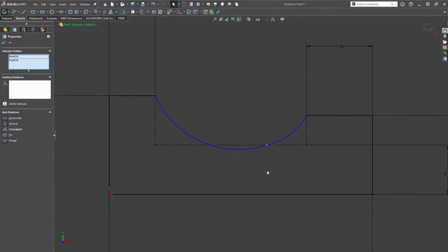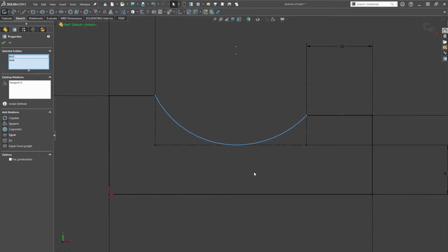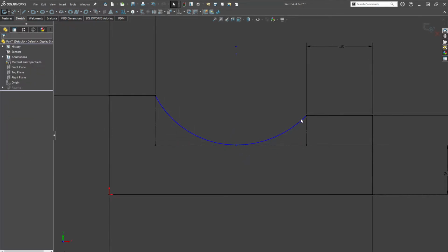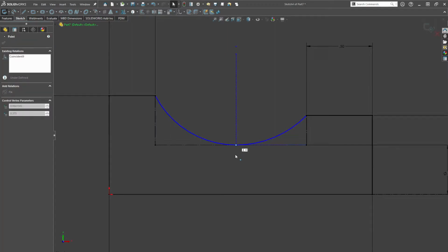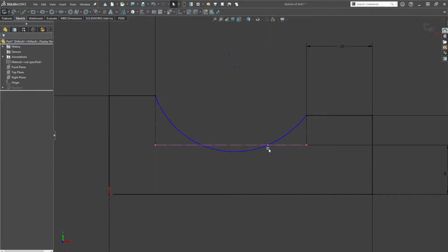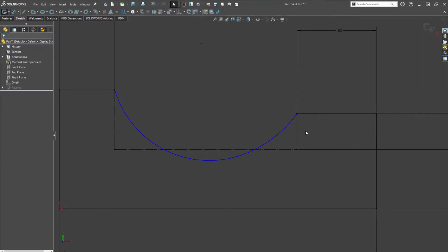So if we put these together so that the points touch, and let's say that we don't necessarily want it to be tangent. We could put this tangent to that. Hey, you guys should be tangent. We can put this point tangent to our original body diameter, but you don't have to. So let's go ahead and get rid of that tangency point. And now the curves are still tangent, but we're not tangent to the line. And furthermore, if I get rid of that, we're not even stuck on that body line anymore. We could make the pawn have a thicker body or an even thinner body. Let's do this scallop. The pawn's kind of scalloped now.